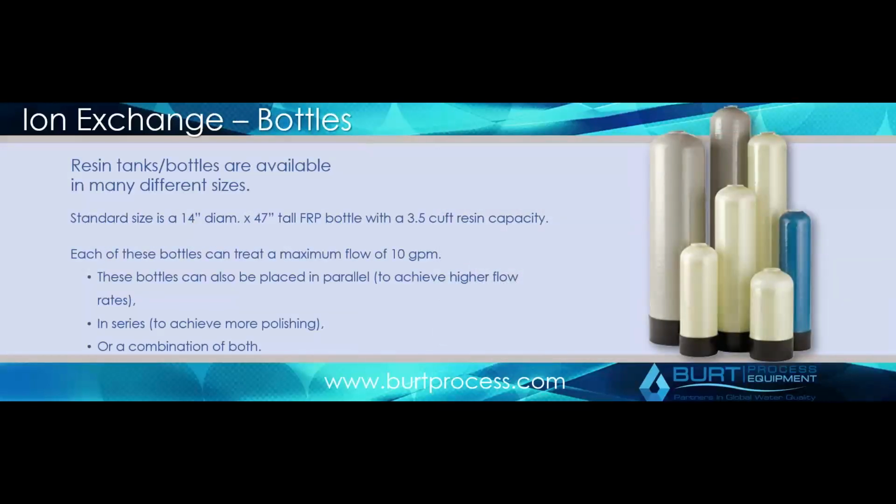But what is just deionization? Well, deionization is essentially you have what's basically referred to as a resin bead. On that bead, if it's a mixed bed resin, which means you have both cationic sites and anionic sites, or positive and negative sites on that resin, it's going to target different species, whether that be sodium or whether that be bicarbonate.